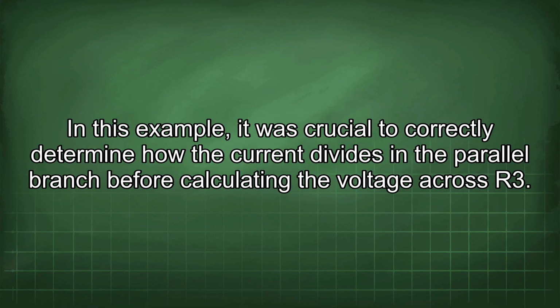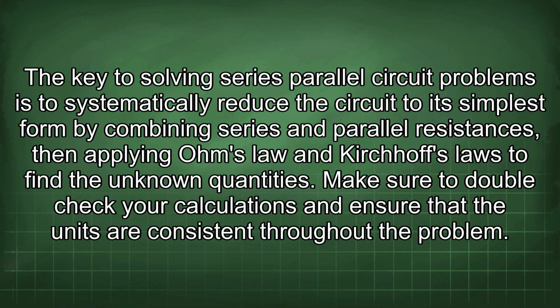In this example, it was crucial to correctly determine how the current divides in the parallel branch before calculating the voltage across R3. The key to solving series parallel circuit problems is to systematically reduce the circuit to its simplest form by combining series and parallel resistances, then applying Ohm's law and Kirchhoff's laws to find the unknown quantities. Make sure to double-check your calculations and ensure that the units are consistent throughout the problem.